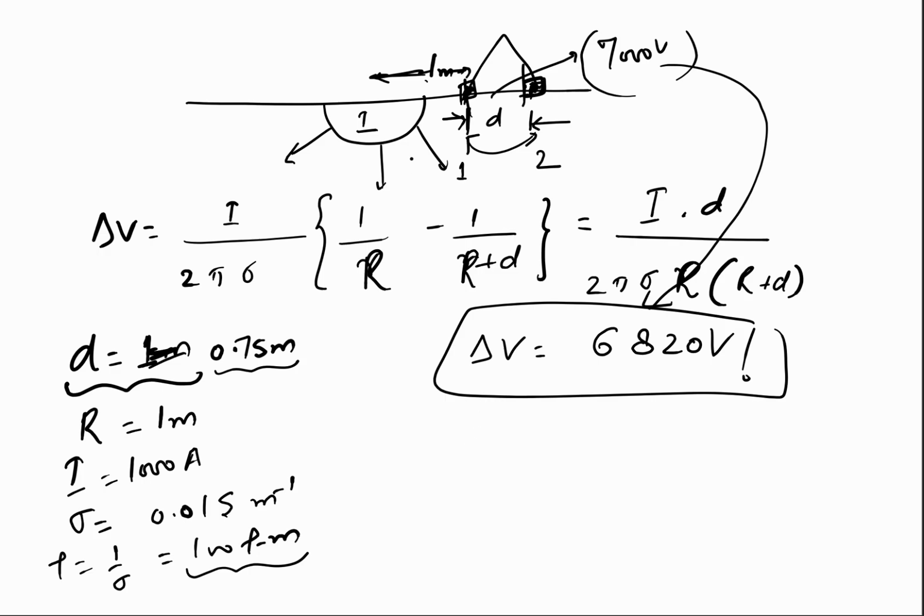So you see, whenever a ground electrode is carrying a fault current, we should be very careful while going near it. We should not go near it, because there will be a hazard of step potential if the design of the substation grounding is not proper. Now this 100 ohm meter is not a very fancy value, it is a very practical value. So this is a very practical case. Of course, we have assumed that the electrode is just on the surface and it is hemispherical.